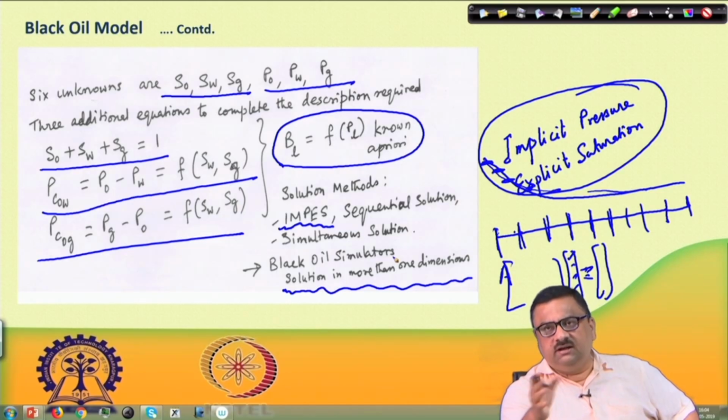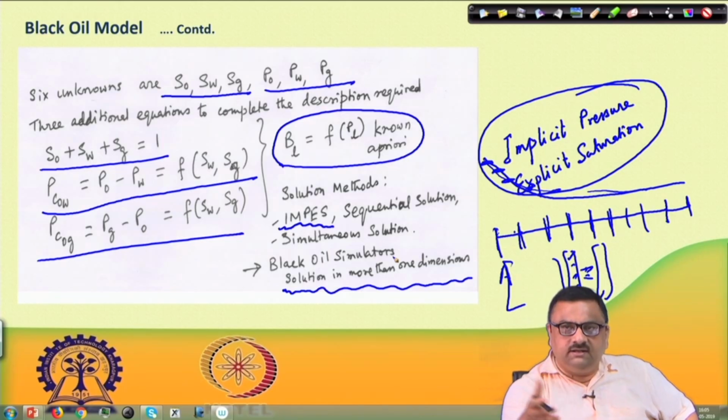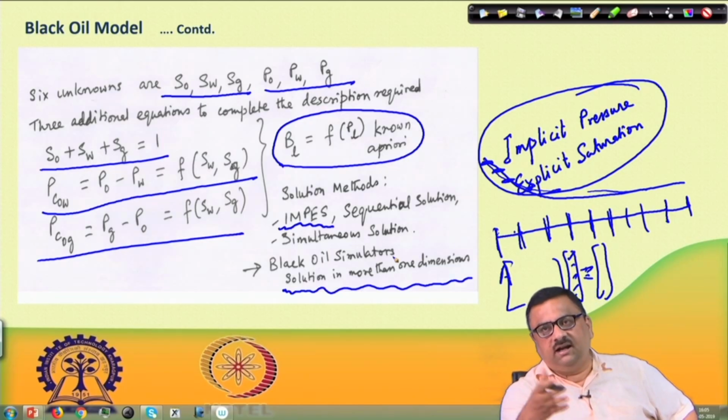Say, for example, the relative permeability curve and all, but there are a lot of other graphics too. The essential treatment would be very similar to what I mentioned, because at the end of the day one has to solve the continuity equation for the three phases. It may not be only one dimension, maybe two or three dimensions. Maybe there would be a fracture in the middle, so one has to account for that, so there would be a fracture permeability. There will not be a single permeability, there will be a layered reservoir, with multiple permeabilities for different zones.